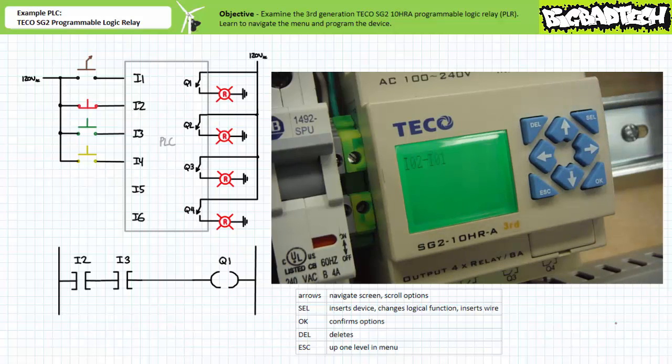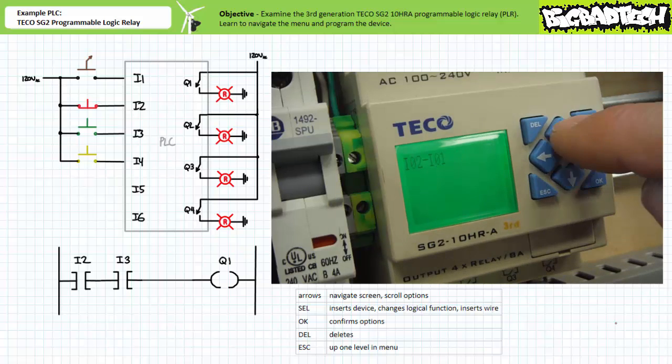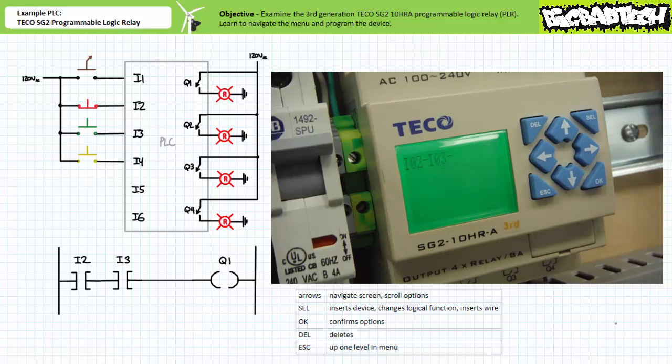Press Select to insert another contact. The device again inserts the default contact I1 as a make instruction. Right arrow to the contact number, increment it to 3. Press OK to confirm I3. We're not going to use the third contact column since our program has only 2 inputs. Press Select 3 times to insert a line and press OK.